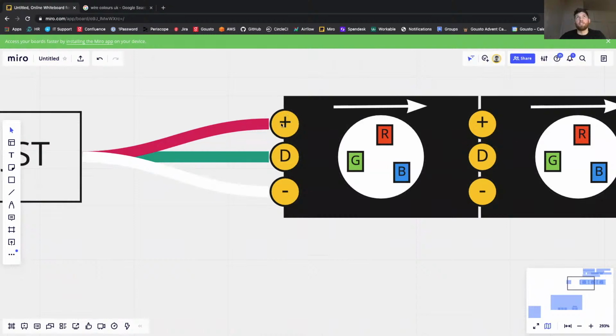And just to zoom in, these symbols are meant to designate what these copper pads function as. So these copper pads are wired inside this printed circuit board into this circuitry that's inside here, that's much more nuanced and complicated than what I've drawn in this diagram. But they essentially provide a physical electronic connection. So these are literal copper pads, which you will be able to see on the circuit board and are required to make that connection.